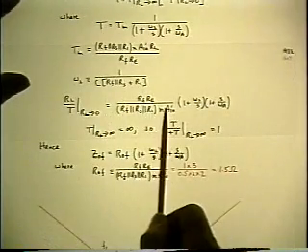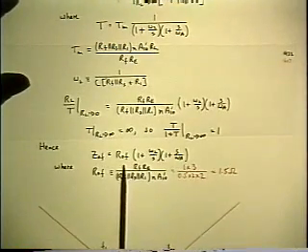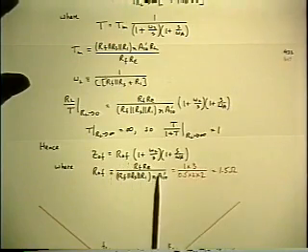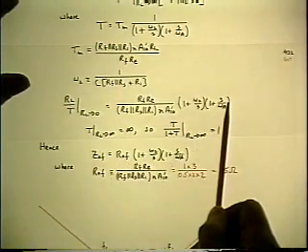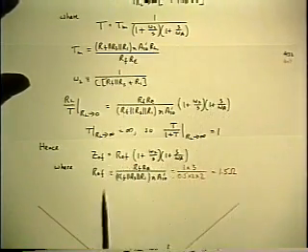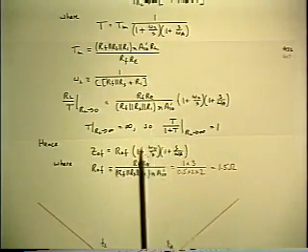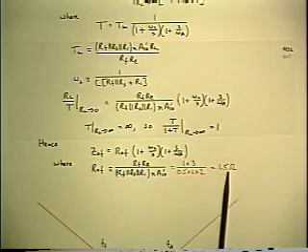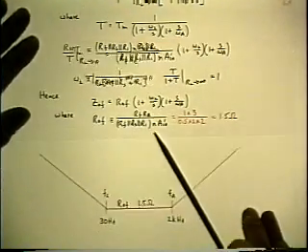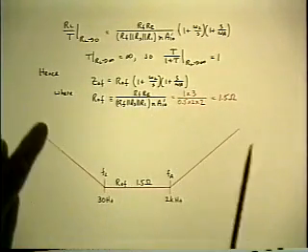The coefficient in front has dimensions of resistance, so we call it the mid-band value of the output resistance with feedback, ROF, and there it is, and it has two corner frequencies, an inverted 0 and a normal 0, which are the same frequencies that were originally in the T. Numerically, the ROF is 1.5 ohms. And then the zeros outside that range cause the closed loop output impedance to rise.